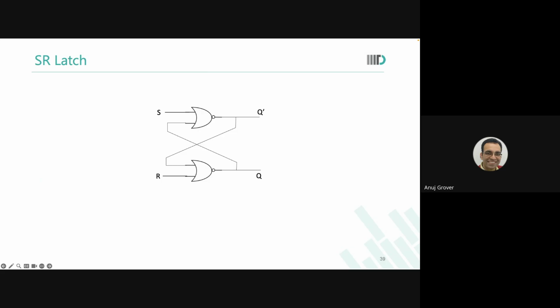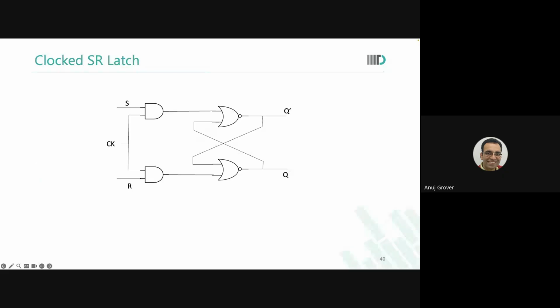So what we actually have is, if you want to store some information and access it at my desired time, then what I really need is a clocked SR latch. And over here, I have two signals, set and reset. If the user does not handle each of those two signals carefully, my latch could go into a random state. I don't want that. I have only one D. Store the D, whatever S has to do, whatever R has to do, let them keep doing it. That is what you want.